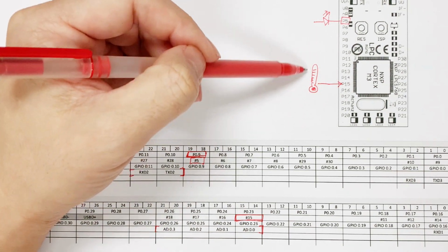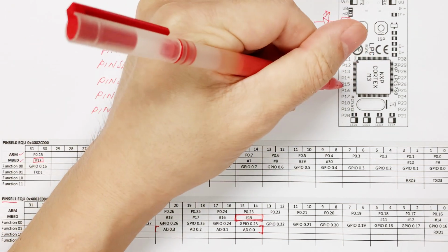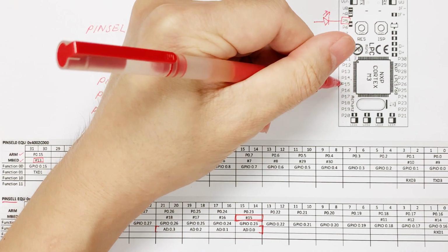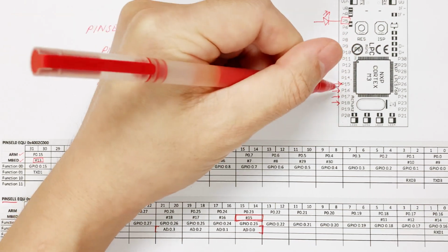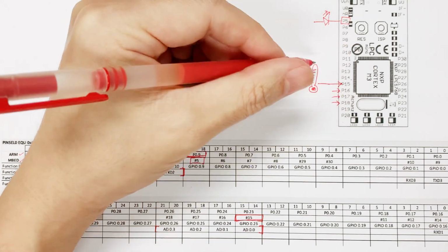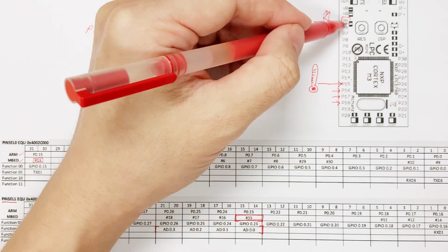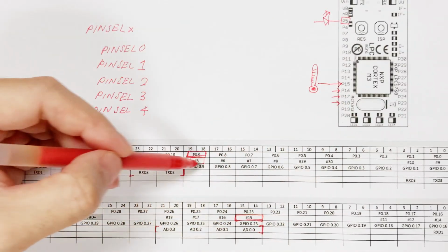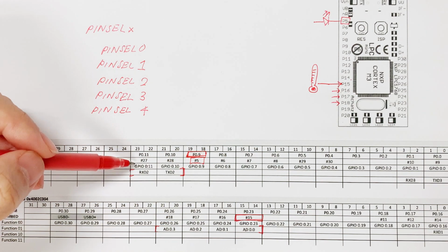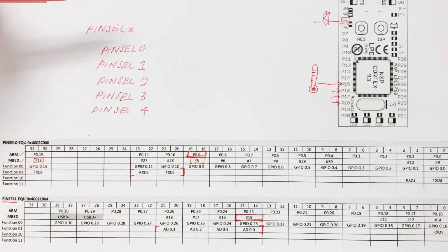In case you have a few analog sensors, the analog pins P15, P16, P17, and P18 are the only pins that allow us to connect any analog input sensors. But of course, the rest of the I/O, from P5 up to P30, can behave as a GPIO. For any digital input or digital output, you are free to choose among them.